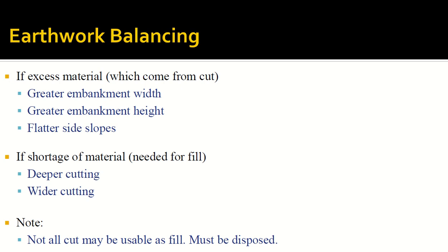You cannot do filling without looking at the properties of the soil you are filling. Okay, so I took the soil from here and I'm going to fill it somewhere else. This was natural soil. It can be anything. It can be rocks, it can be sand, it can be clay, it can be what they call silt, it can be the sand which you find near the beach. So all types of sand is not usable. So you have to test the soil before you start filling.